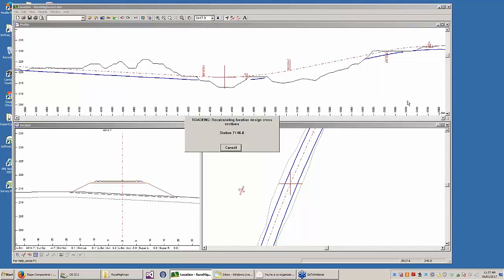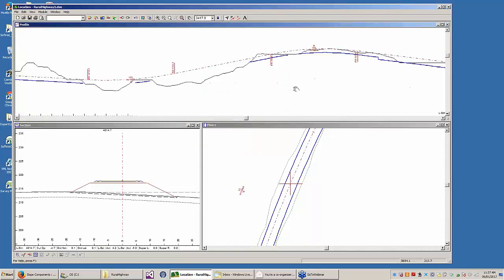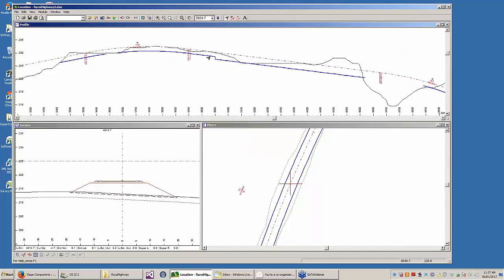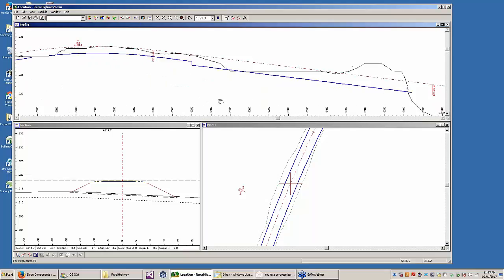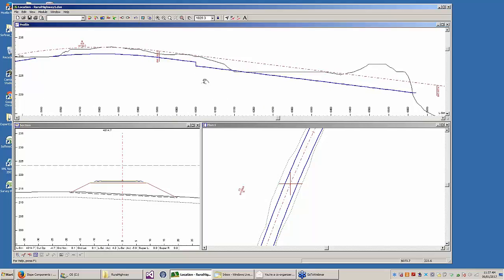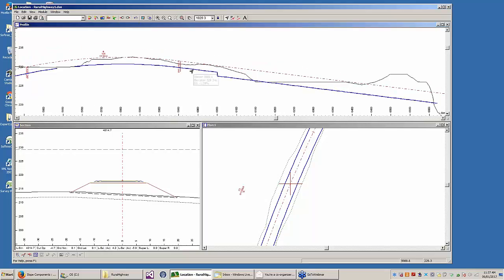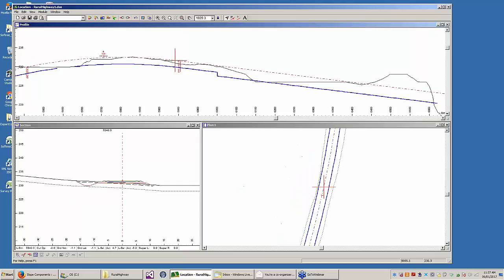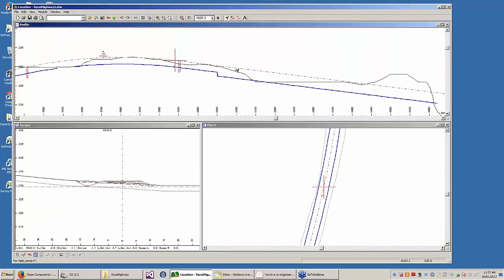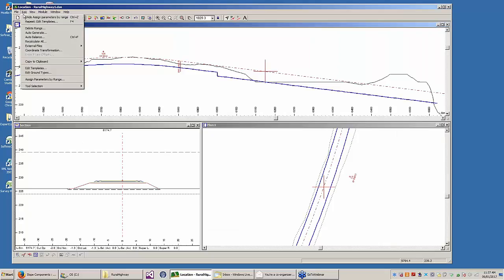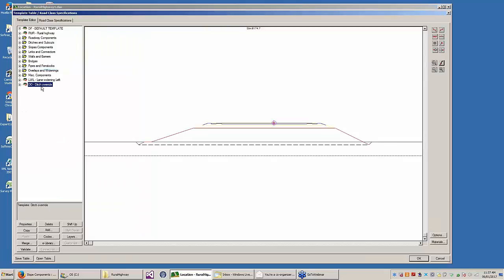6050. There, you can kind of see it. It's jogging down because the ditch depth was deeper than the other ditch. Like, this is one template in here. Just look at that. Go to template editor, edit templates. So that's the rural highway. If we go into this section of road here, click on a point, edit templates, and we're in the ditch override section. And the ditch is by default a little bit deeper, so we're seeing it.